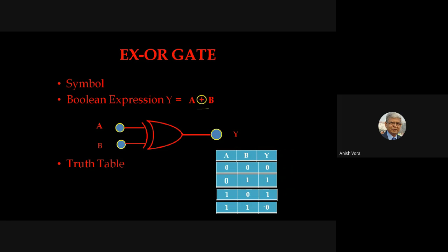તમે અહીંયા જુઓ ને તો એક જે લાસ્ટ કન્ડિશન છે ને 1-1, OR ગેટ નું ટ્રુથ ટેબલ જો તમને અત્યારે યાદ હોય ને તો ધીસ કન્ડિશન, બાકી ત્રણે કન્ડિશન આપણી જે OR ગેટ ની છે ને એ સેમ છે. એક આ જ કન્ડિશન લાસ્ટ કન્ડિશનમાં જ્યારે બંને ઇનપુટ હાઈ હોય તો OR ગેટમાં અહીંયા હાઈ આઉટપુટ આવે. બટ નાઉ in exclusive OR condition, this last condition is excluded, right? અહીંયા આપણે 1 ની બદલે 0 લઈ લીધું.